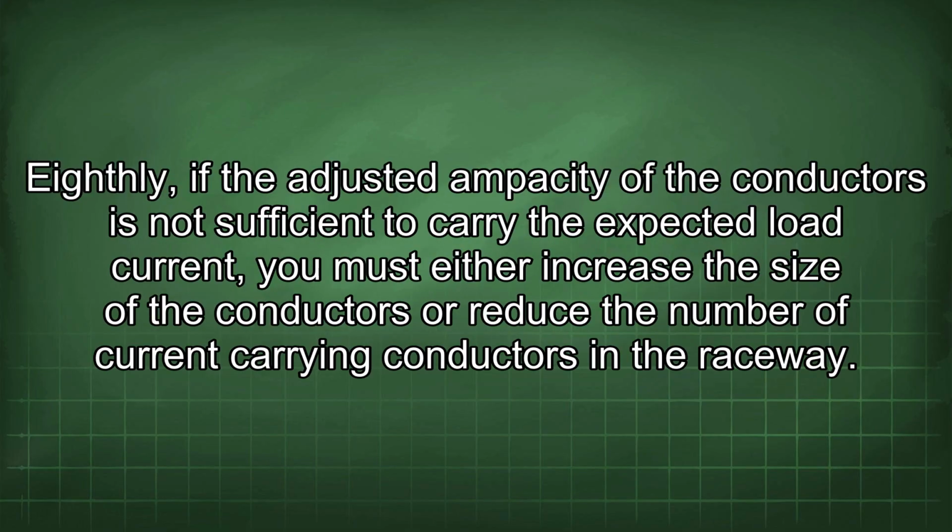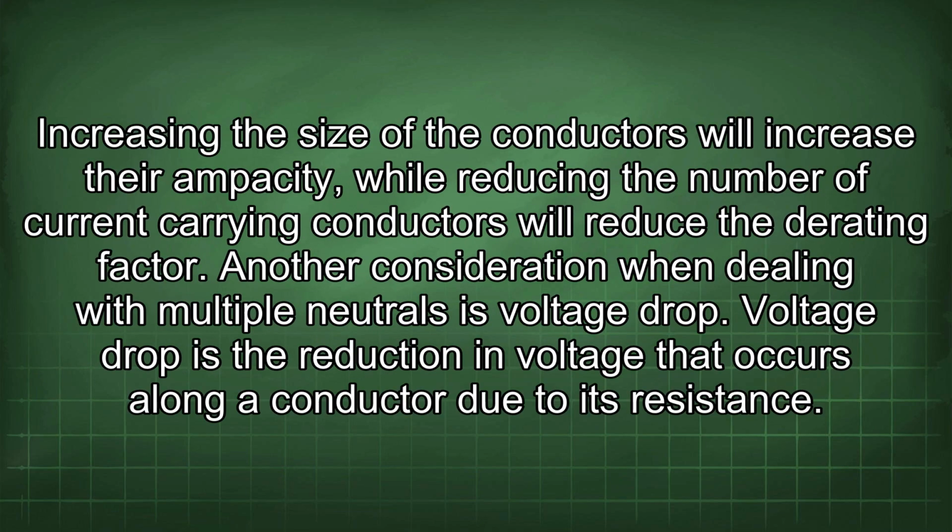Eighthly, if the adjusted ampacity of the conductors is not sufficient to carry the expected load current, you must either increase the size of the conductors or reduce the number of current carrying conductors in the raceway. Increasing the size of the conductors will increase their ampacity, while reducing the number of current carrying conductors will reduce the derating factor. Another consideration when dealing with multiple neutrals is voltage drop.